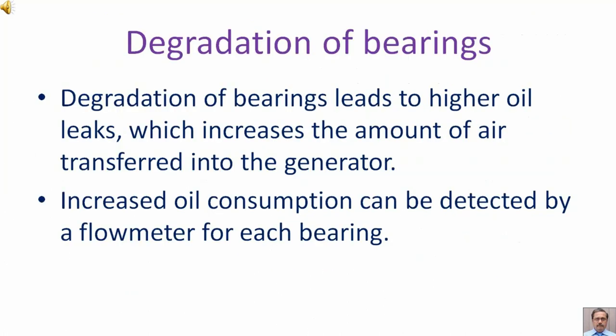Degradation of bearings leads to higher oil leaks, which increases the amount of air transferred into the generator. Increased oil consumption can be detected by a flow meter for each bearing.